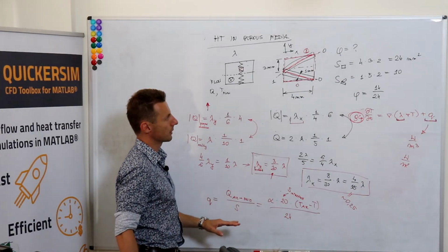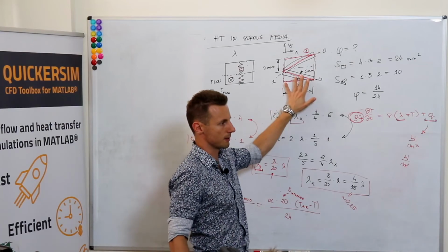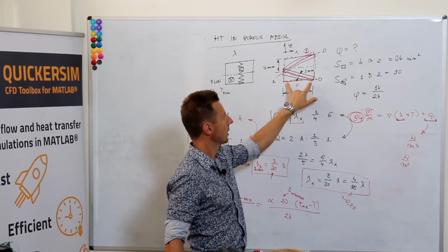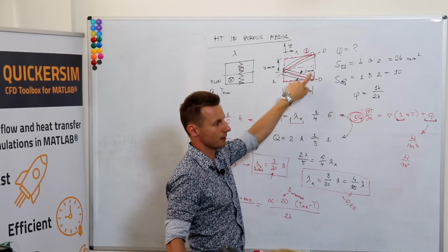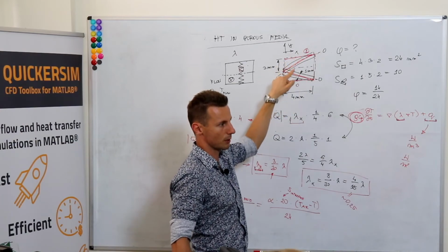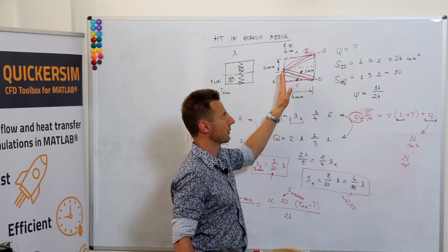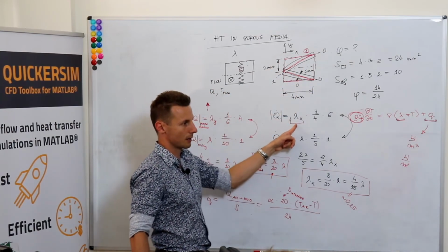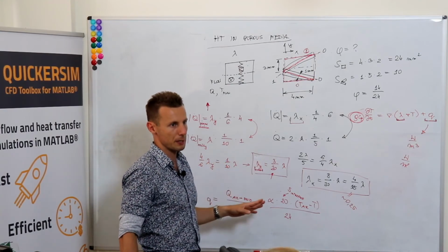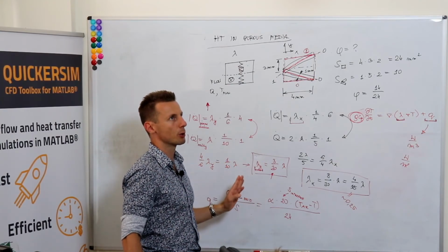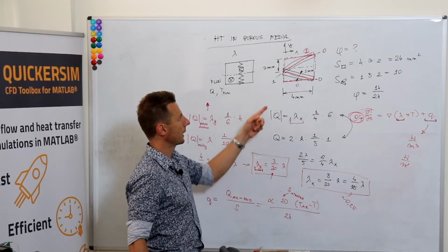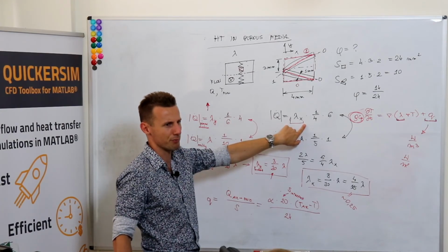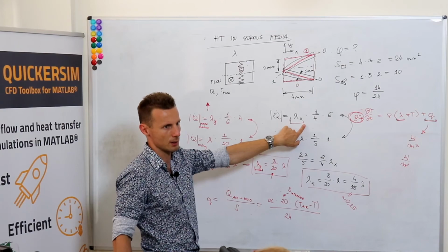The only thing we did differently is I think we have used our Quickersim CFD toolbox to really prepare such a two-dimensional geometry of the representative element and apply the boundary condition to calculate flow in it, to calculate the heat conduction in each direction, and then calculate lambda x, lambda y. But believe me, taking the real numerical results and comparing it against such an estimation was within the margin of, I think, 3–4%. It was really very, very accurate.